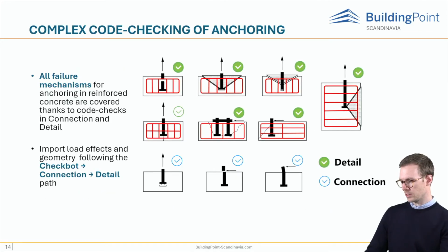Together, the two applications cover all failure mechanisms for anchoring in reinforced concrete. In other words, in the connection application, the pull-out and steel failure on the lever arm are covered. And in the detail application, the steel failure, the concrete cone failure, and the splitting failure are covered.